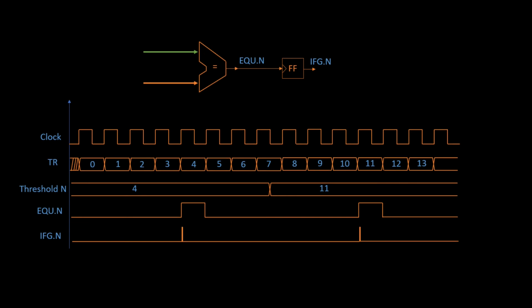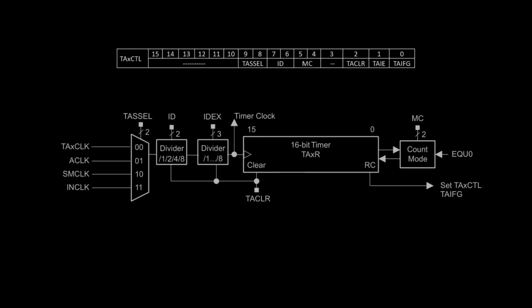So this is an interesting system of communicating a hardware event to the processor. In the MSP430, there is one configuration register specific to configure the clock time reference and the counter, and another configuration register for the channel of the timer.